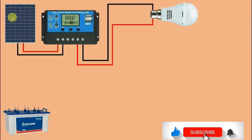The only problem is the solar panels could be generating a higher voltage than that of the DC bulb. So there is the need for a charge controller to reduce the amount of voltage coming from the panel to the load. The charge controller regulates the amount of voltage that comes from the panel.